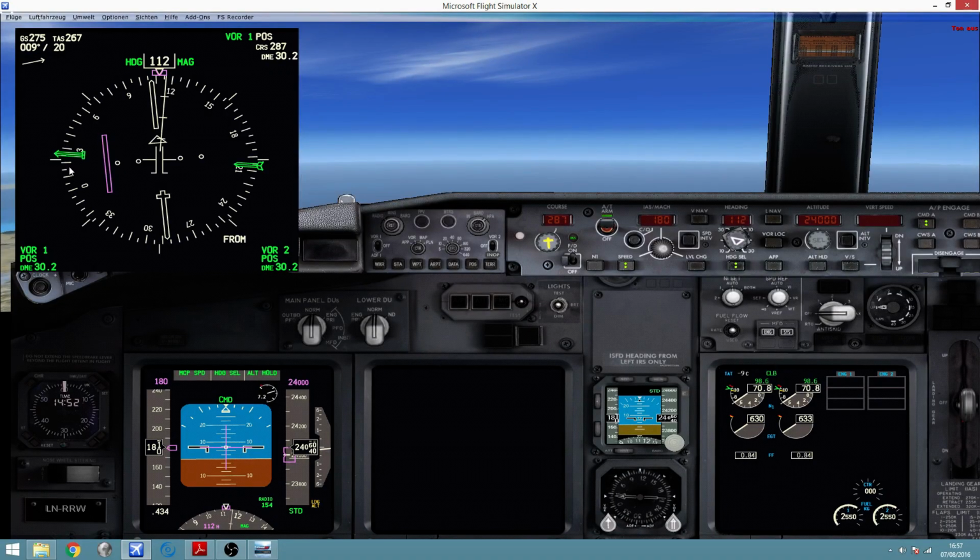If the VOR is to the northeast of your position, as this arrow is showing, it's telling you that the VOR is on track 025 more or less. This is indicating that you are on the radial that is exactly the opposite, which is 225 or 220. All right, so you are on radial 220, 30 miles out.